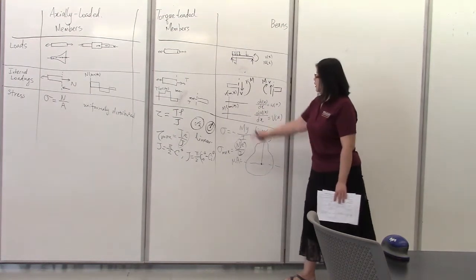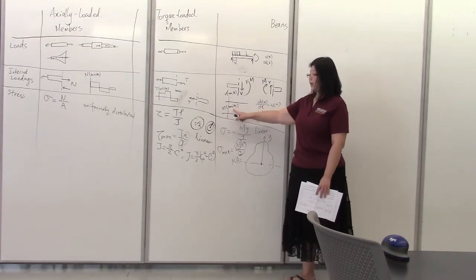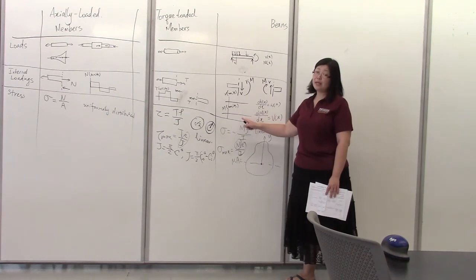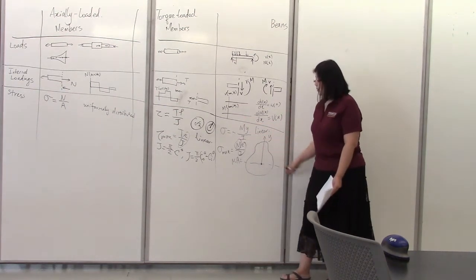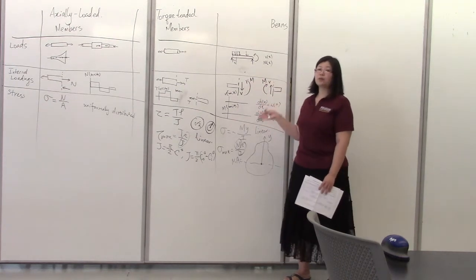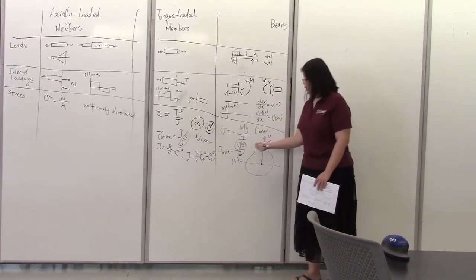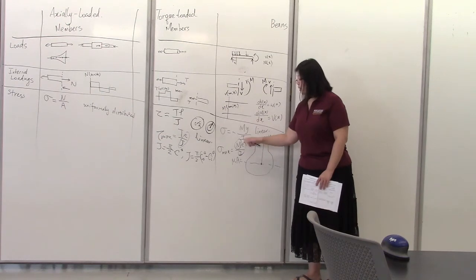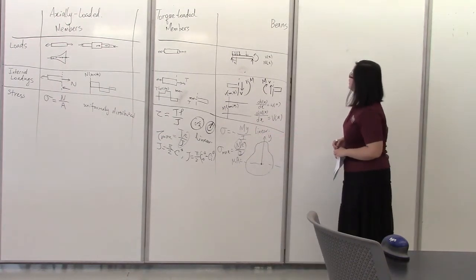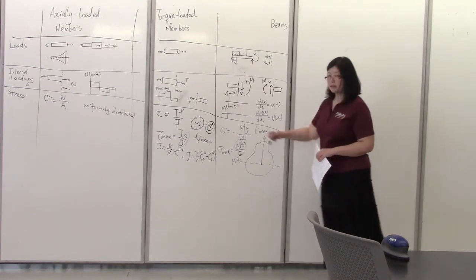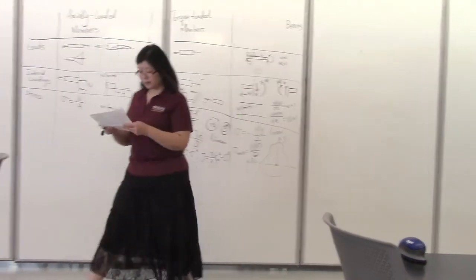But sometimes, if the m could show a maximum positive and a maximum negative, and the beam cross-section is asymmetric with respect to the neutral axis, then you'd have to check both cross-sections to see whichever gives you a combination of this product that is a maximum. So that's the beam stress. Again, it's linear with respect to the neutral axis.